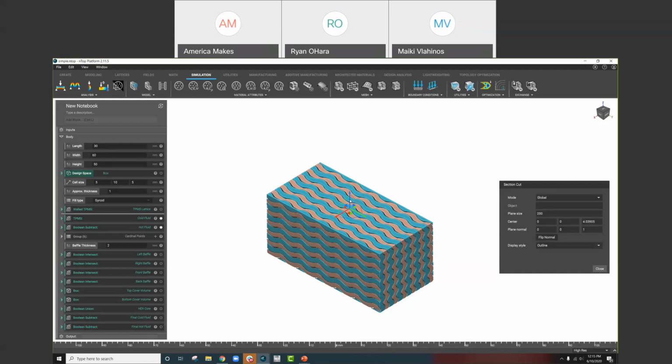So what we can do, and this is part of a collective effort of engineers, is to try and characterize some of these shapes and aspect ratios. So if the flow is moving from right to left in this direction, maybe we want to stretch and morph the unit cell in the y-axis, or the direction parallel to flow, to try and reduce that pressure drop a little bit, but at the same time continuing to go well above and beyond traditional means of heat exchangers, the shell and tube, for example.